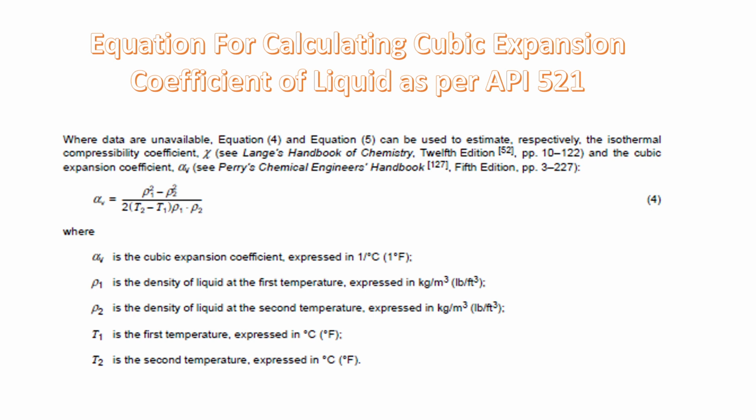So here is the formula to calculate the expansion coefficient of particular fluids. I'll just explain one example to you. Suppose we are transferring xylene, toluene, or any solvent, acetic acid, from the tank farm to the plant, and the length is between 200 meters to 650, 600, whatever it may be. As you know, there is a distance between the tank farm and the plant. So based on that distance, the transfer of the liquid usually takes place at room temperature. Okay, so we need to calculate the cubical expansion coefficient.